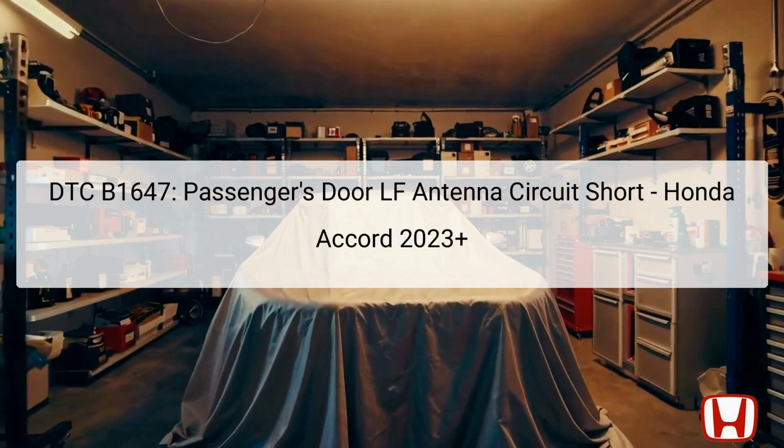DTC B1647 refers to a fault in the passenger's door left front LF antenna circuit in the Honda Accord 2023 model. This diagnostic trouble code indicates that the body control module has detected an earth fault in the LF antenna line. The body control module plays a vital role in overseeing various electrical functions in the vehicle, including the antenna circuit, which is crucial for keyless entry and other electronic features.